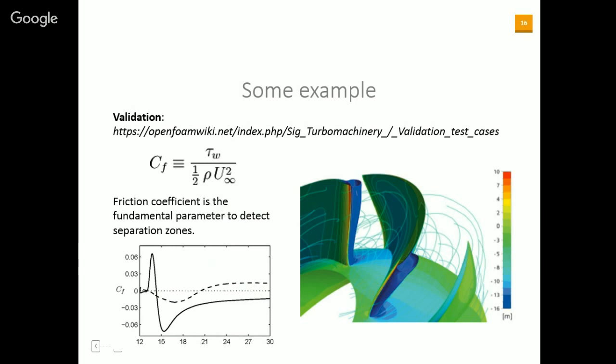It is important during the designing phase to minimize the separation zones by modifying the geometry of the CAD, of the blade, of the pump in general, also because having huge separated flow may also lead to cavitation phenomena.